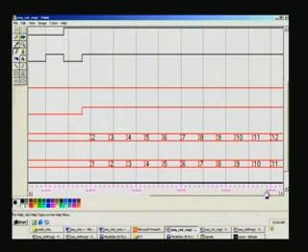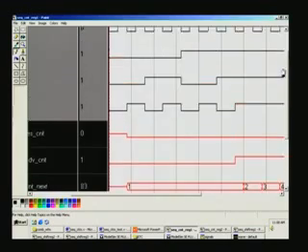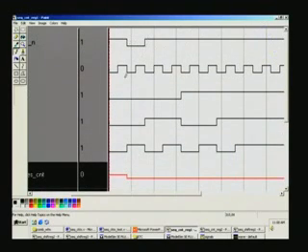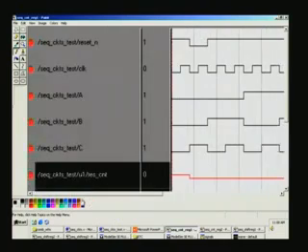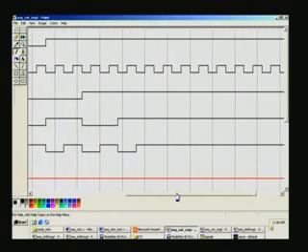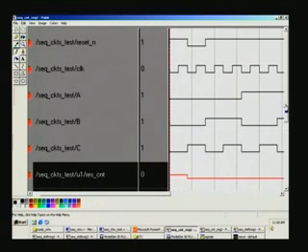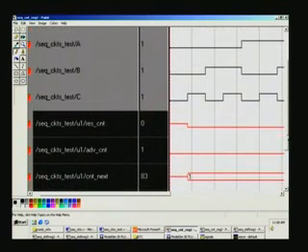This is quite a long one. So I had taken the very first few of this, and then at the fag end another file. So you see here, because advance count is 1, counting is taking place, and this got reset here because of the reset pulse here, right at this point, and this is the clock waveform. This is ABC here. So now let us see at what point of time reset count is going high. This ABC is here.